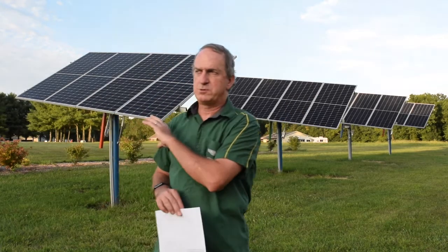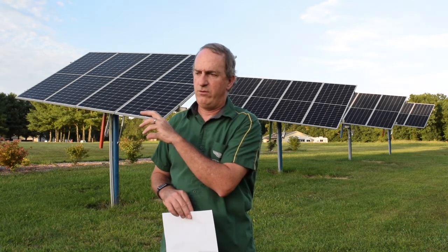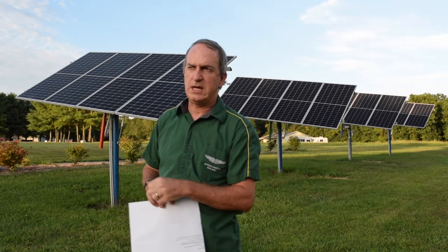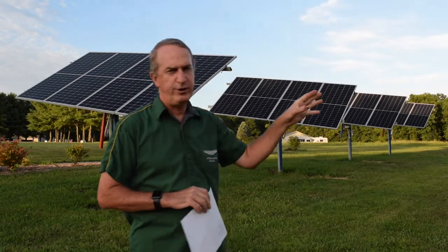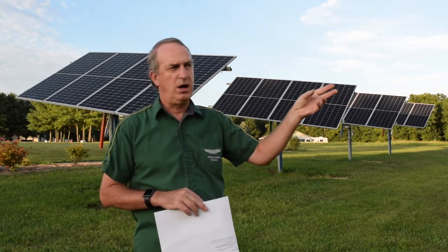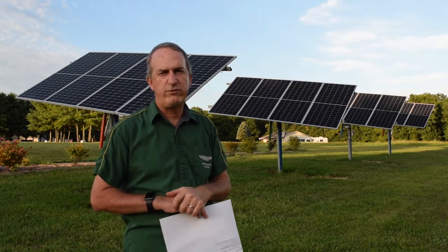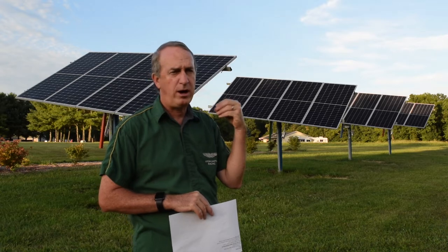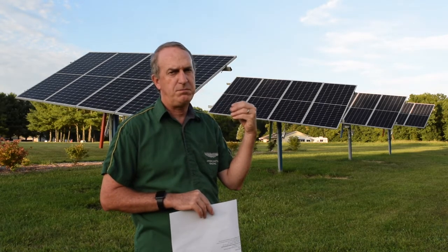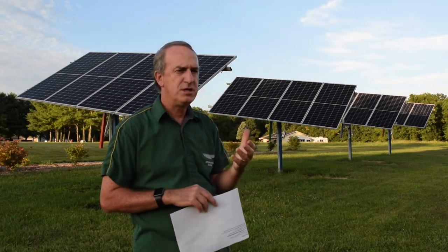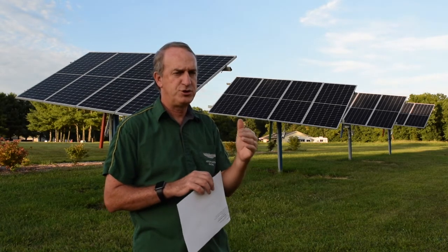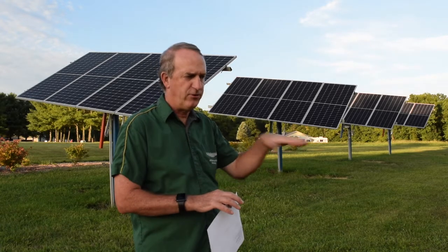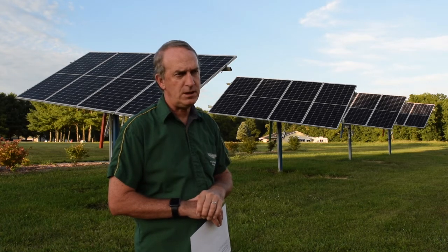First off, your solar panels are making their voltage, and then the optimizer sees that voltage, but it says, well, I'm going to make 1 volt and send it down the wire back to the inverter. The inverter sees the 1 volt, counts them up, and says, okay, I've got several 1 volts coming in, so I'm going to turn the system on now. So it sends a signal through the same wire back to the optimizers, and then the optimizers adjust their output voltage and current to meet the commands of the inverter, and then deliver that power back to the inverter.